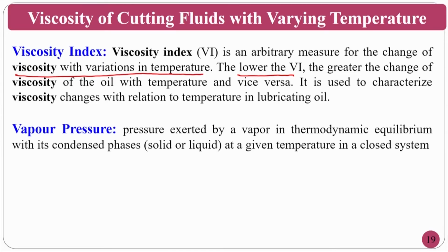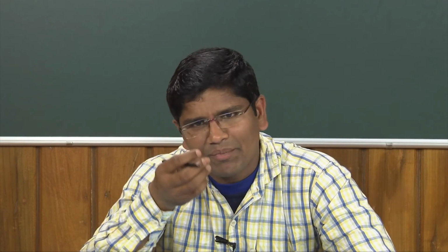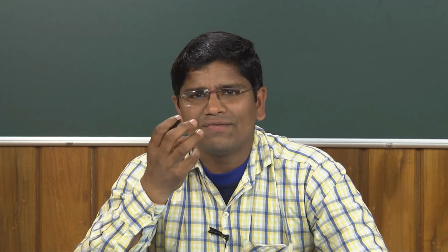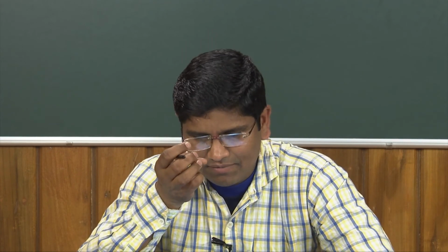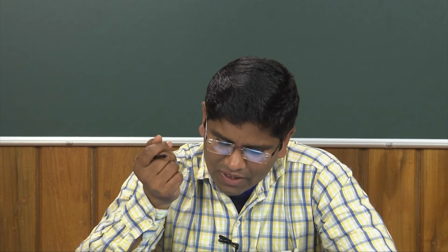This is the pressure exerted by the vapor in thermodynamic equilibrium with its condensed phases. That means, if I am sending a cutting fluid into the machining region, the cutting fluid has to penetrate into that region. At the same time, because of the temperature, it will change itself into vapor, because intermolecular distance will increase because of gaining thermal energy. That is why it will convert into the vapor.